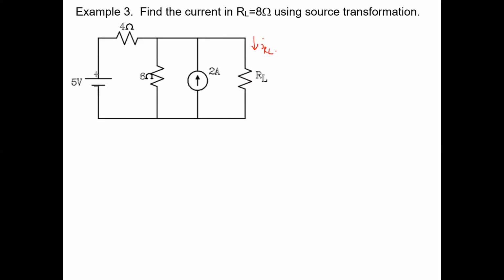Now, once you get good at source transforms, these are actually nice tools to simplify the circuit a little bit. If you can do an easy source transform, you can reduce the number of components. It simplifies what comes next, like nodal or mesh. I tend not to use it too much. We tend to go towards the big, heavy tool, which is nodal analysis, but this is actually a nice tool, and it leads us to an appreciation of Thevenin equivalence.